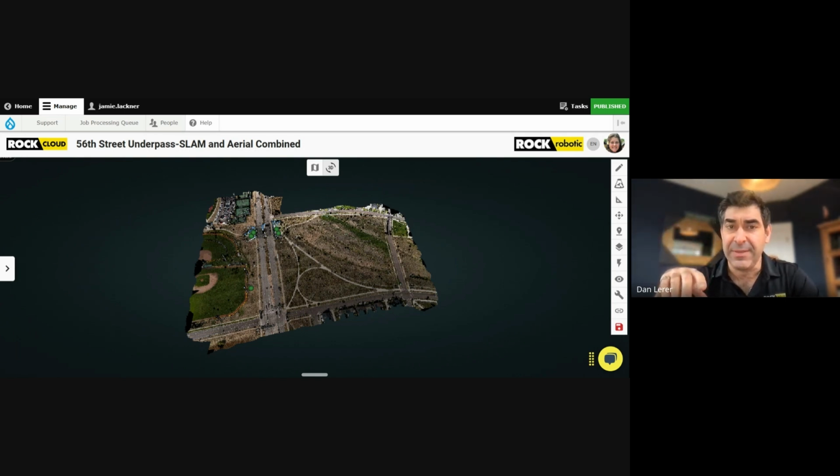We collected millions of points, all the detailed features like the curbs, the parking lot lines, and the building footprints. We used ground control points and captured them with RTK to ensure precise alignment with the coordinate system and projection. The benefit for you is faster data collection, reduced on-site risks, and comprehensive coverage, even under the tree canopies and under the bridge underpass, which you'll see as well.